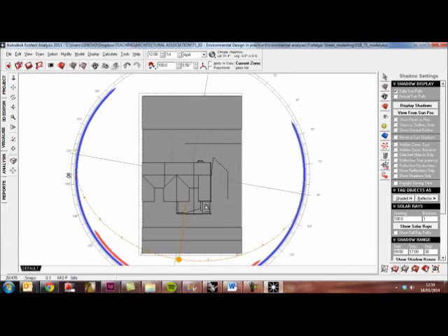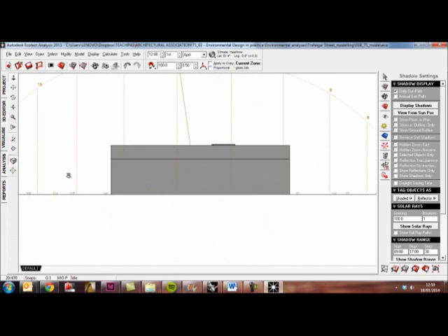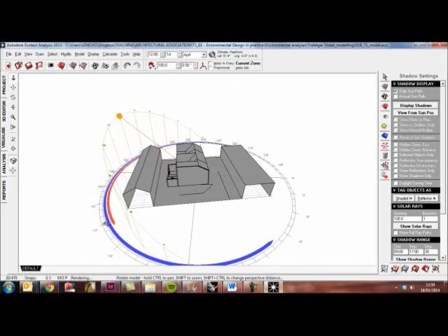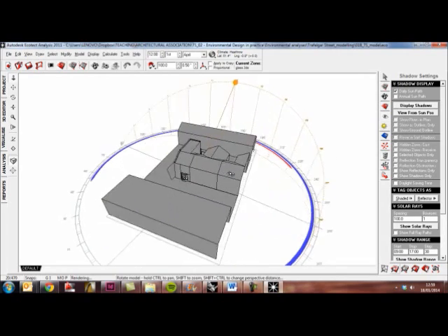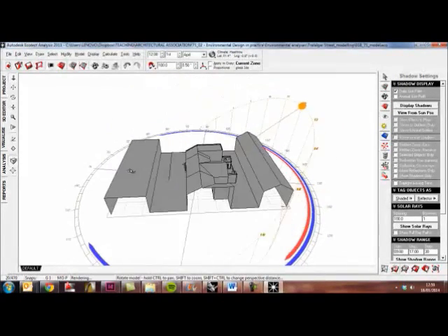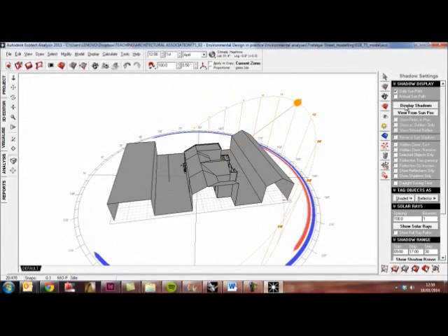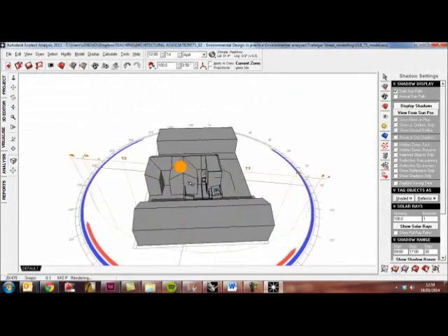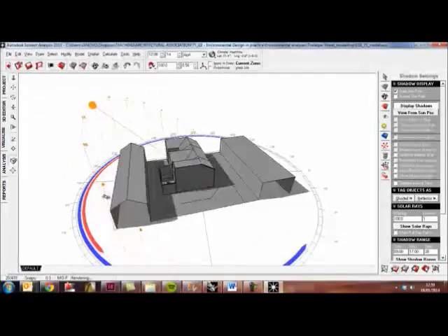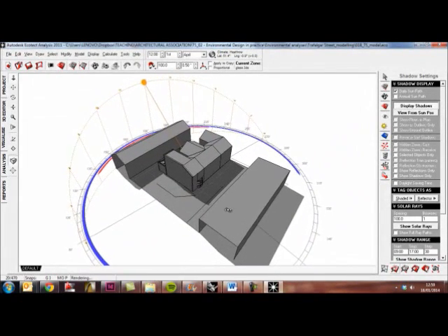Which means when I go to visualize, and I click now on the other F keys, F8 gets me back to perspective. It means now that the position of the sun relative to my house is correct. So when I turn on the shadows, as display shadows, that is actually the shadows that will be cast in terms of the position of the sun. Right, for the exercises that are about to follow, that is how we get Ecotect models into Ecotect from Rhino.